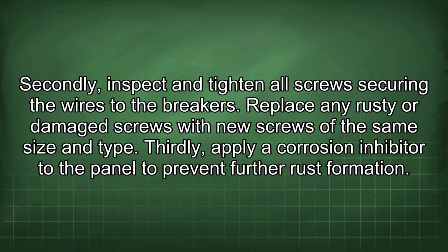Secondly, inspect and tighten all screws securing the wires to the breakers. Replace any rusty or damaged screws with new screws of the same size and type. Thirdly, apply a corrosion inhibitor to the panel to prevent further rust formation.